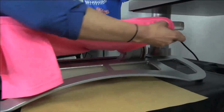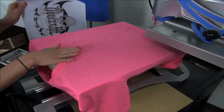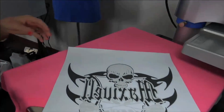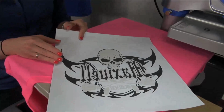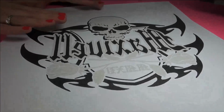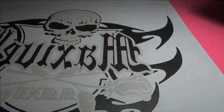I'm going to load my garment onto the heat press. The first step with any heat transfer is going to be, of course, loading the garment and getting it ready for the application with a preheat. What I'm using here for the application is an ink transfer. Separate from other transfer styles, this is commonly called a plastisol or a screen printed ink transfer. The reason being is this is a plastisol or screen printed ink that has been screen printed, instead of on a garment, on a white release paper or a transfer paper. And it also has a powder adhesive on it.